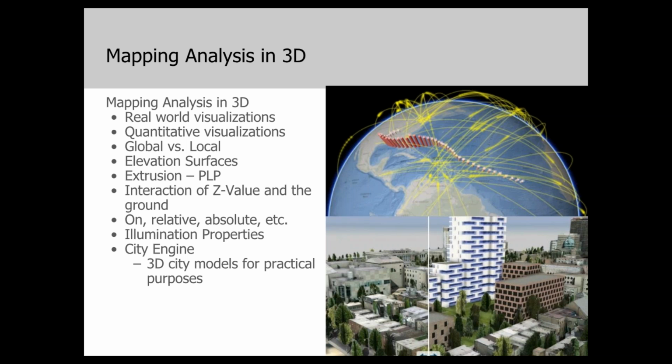Elevation surfaces are important, especially when we get down to the next bullet point of extrusion. Esri starts you off with an elevation surface known as ground. It's just kind of the default surface. However, you can plug in your own. That's always really important to some folks. And it's important when you're extruding features and when you're draping raster data sets over the Earth.